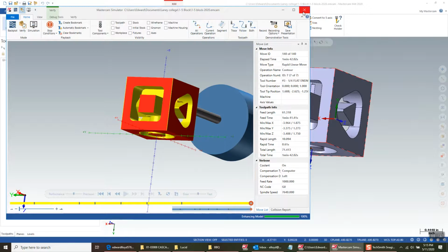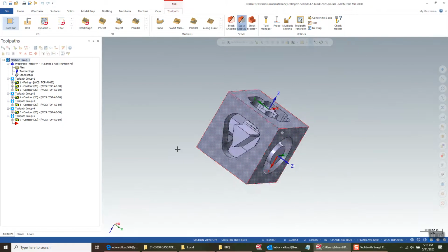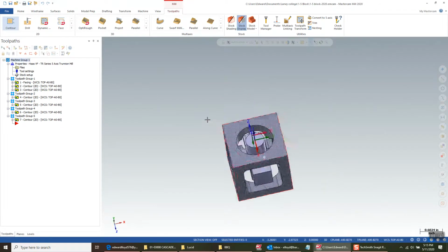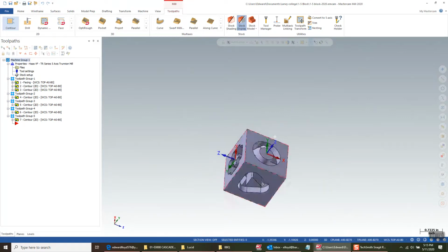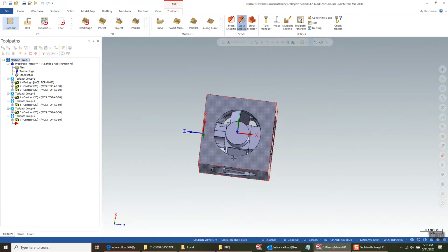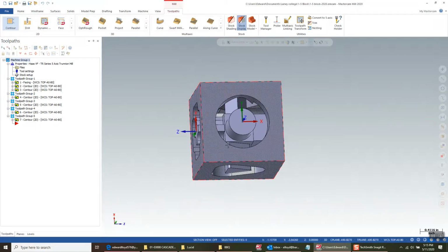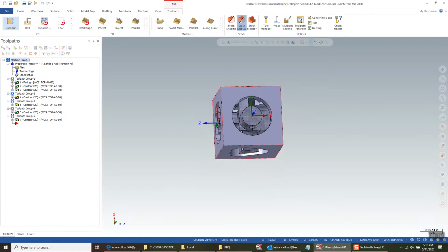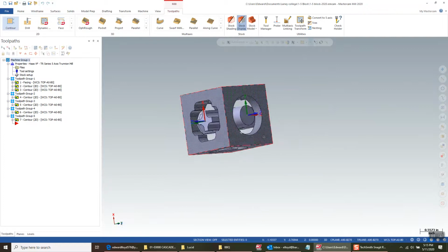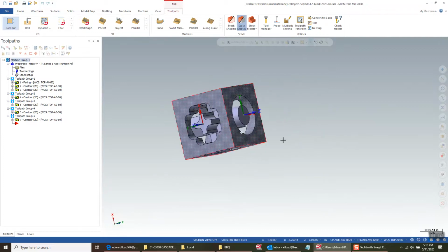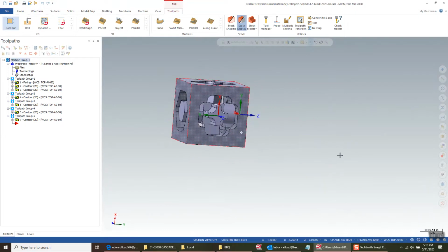So, some things to keep in mind doing this method. Now, when we did the real one, after we would cut the shape, then we would come back with the chamfer and deburr the edges. So that had kind of a safety effect in that there was a tool change at every rotation. So we didn't really have to worry about clearance.